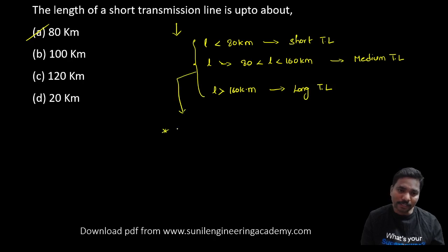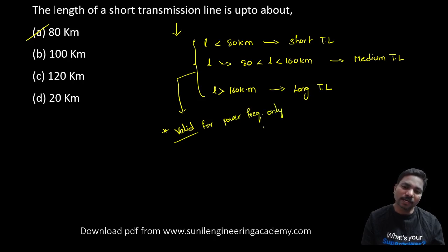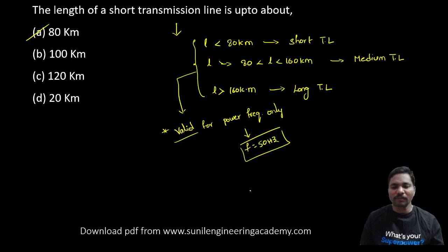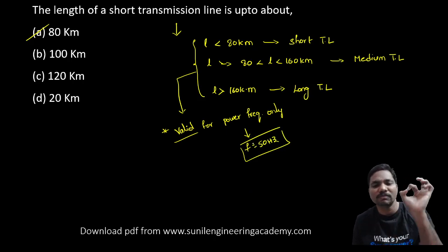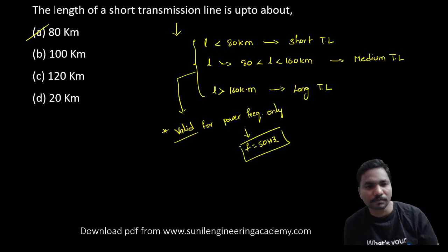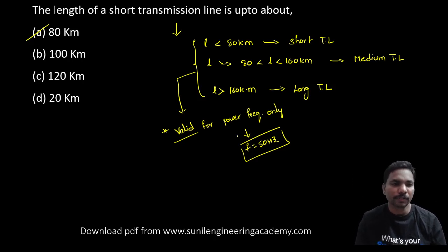All this classification is valid, and this is very important. Here is the key point you have to learn: this classification is valid for power frequency only. What is the power frequency? Frequency is 50 hertz. If the frequency is greater than 50 hertz, this classification is not valid.